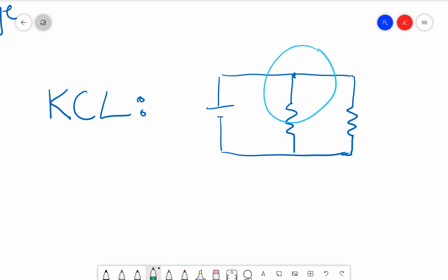So into this junction, we're getting one source of current. That's coming from this battery. The current is going like this, like this, like this, and is going into the junction. One source of current. Coming out of the junction, we have two new paths of current. Current can go through this load, or it can come around here and go through this load. And what Kirchhoff's current law says is that the sum of the current that enters it, so the green line, is going to have to equal the current that exits it, so the red line.